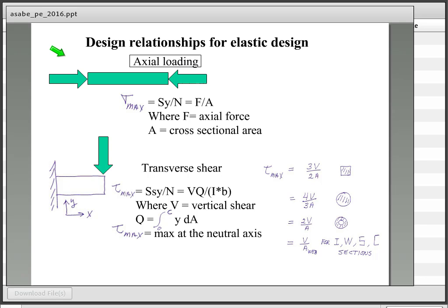Some parts get designed over into the plastic range, perhaps, like ROP structures on tractors. They're designed to absorb energy, and so deformation is allowed and expected in those applications. But for most parts, we're designing well below the yield stress.